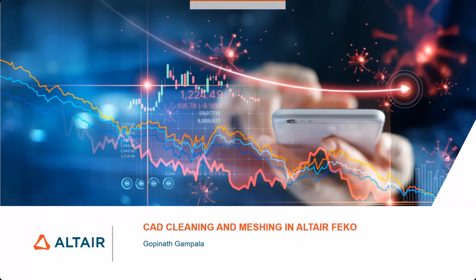of the results. The main reason for faulty CAD is the difference in CAD tolerances between different tools when exchanging the models. So having some basic CAD fixing tools will come in handy in any tool, including Feko, and that is the focus of this topic.